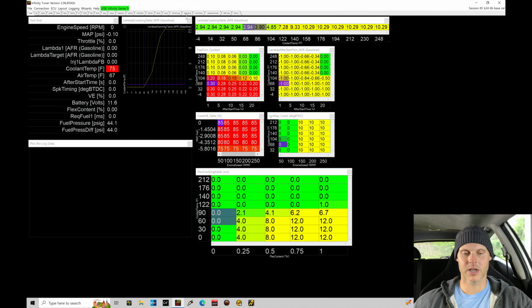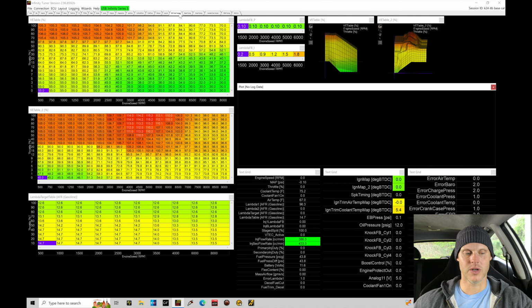If we go in here and take a look at our VE tuning table, we know we've changed our calibration strategy to Alpha-N, and throttle position is what we have feeding our load input to our VE table. We can also see that here in VE table 2. So we can verify, at least just taking a look at our table that we've built in that base map tutorial, so the last 2 tutorials, this is definitely the file. We've imported everything. So now we're ready to do our basic sensor check.